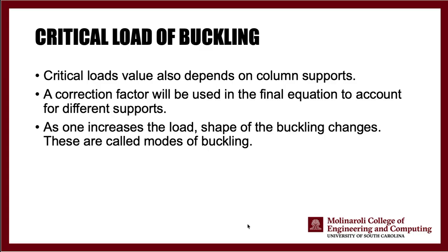Of course, as we said in the beginning, these critical load values depend heavily on the column supports. In order to bring in the influence of supports in our equation, we are going to bring a correction factor in the equation that we're going to talk about later.